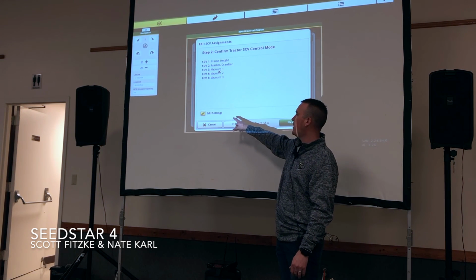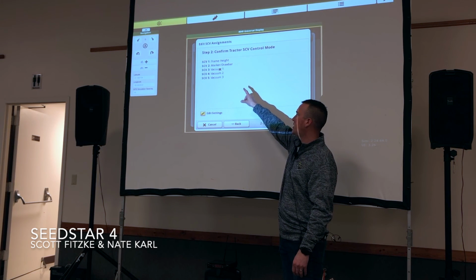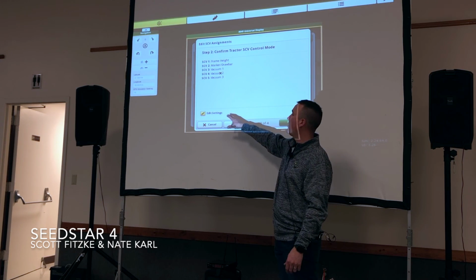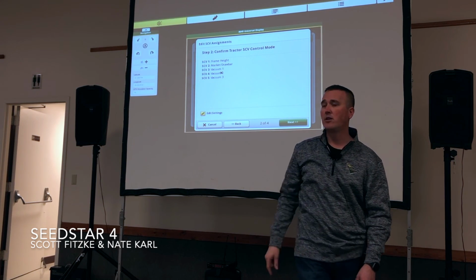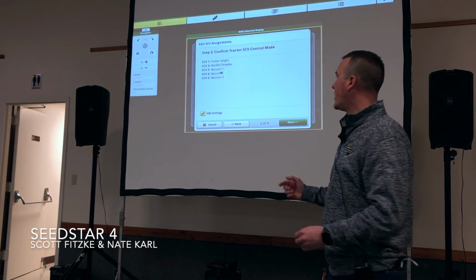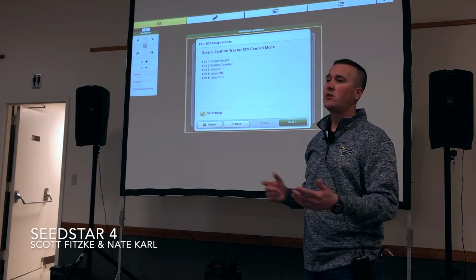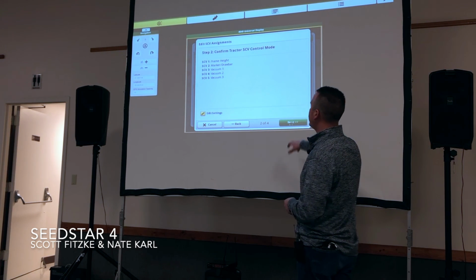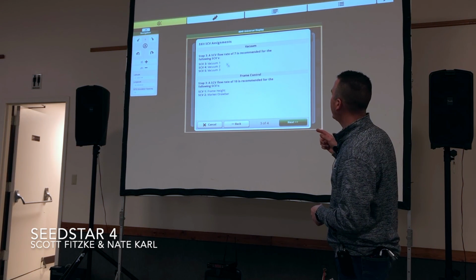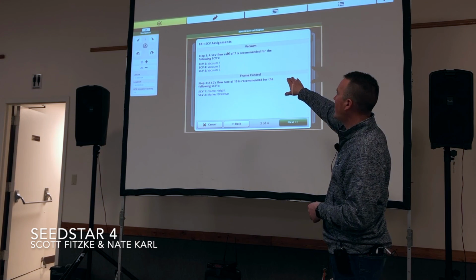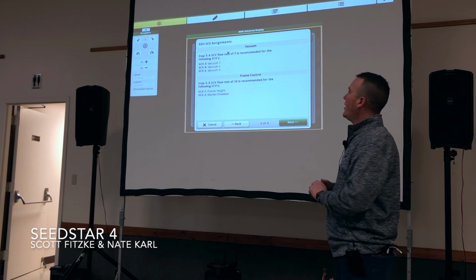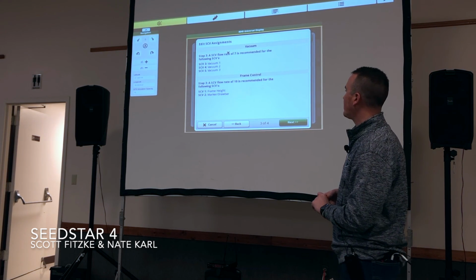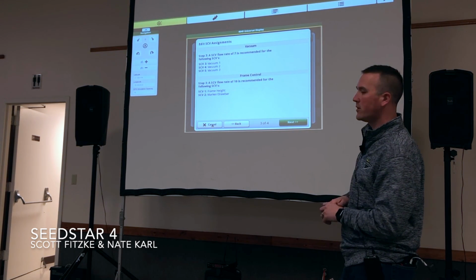And the biggest thing here is we want to make sure that we have the right vacuum set up with the right SCVs. Now you can go change them and move them around, or just edit them in the settings down here at the bottom. What that's doing is it's really telling the tractor which SCVs it needs to use to run that vacuum. Next one here, the last thing it's really going to do before it totally kicks over, it's going to tell you to set that at a rate of 7 as a good starting point. And then from there it's going to try to automatically adjust when you first put that system on. We'll cancel, otherwise it'll lock up our simulator.